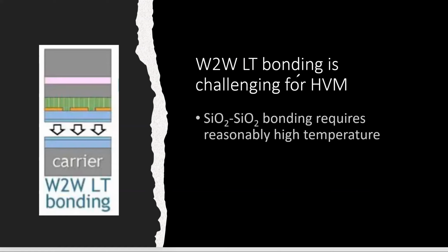Low temperature bonding is the ideal world. You bond them together, you wash it, and you bond them together with some kind of pre-treatment like plasma and all that. Yeah, fine. You bond together using a low temperature bonding process. You could bond it, but can you guarantee it with a high yield? That's the key.